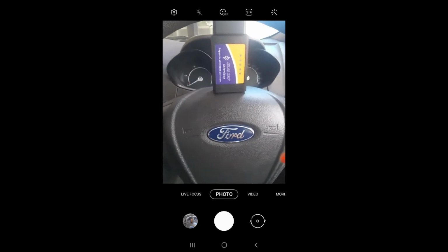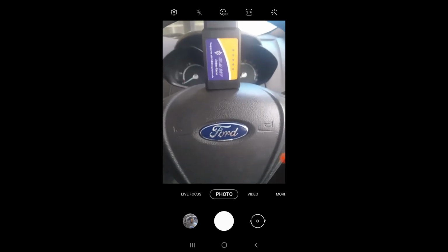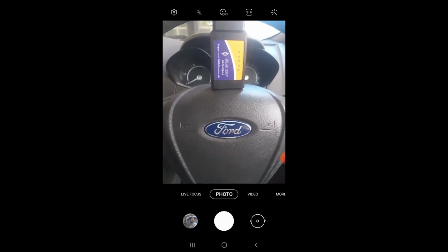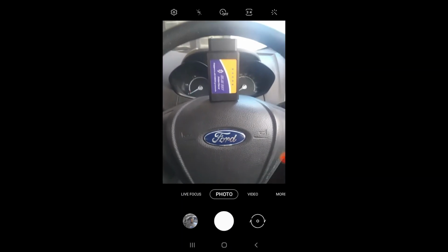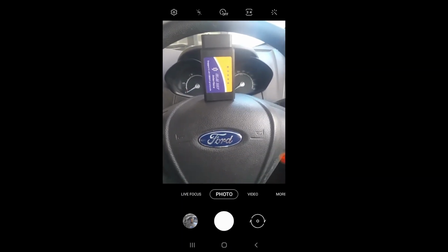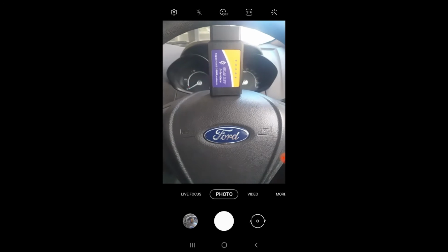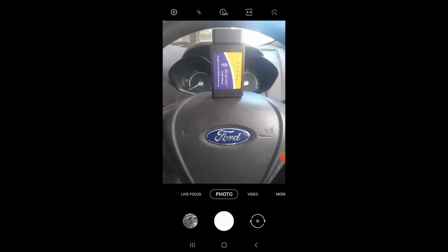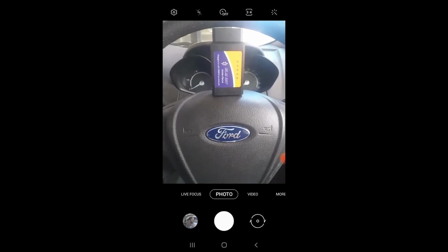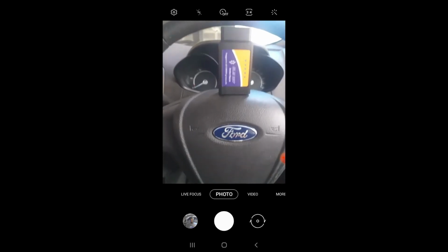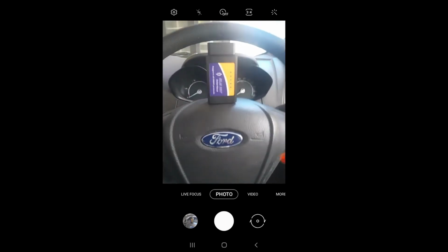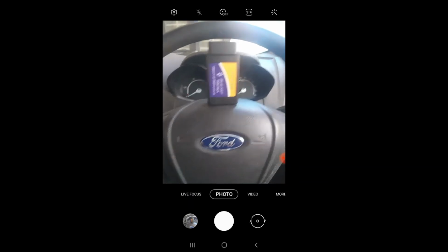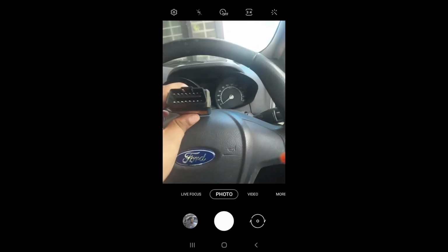We can also talk about PIDs, ID 7DF and ID 7E8, hexadecimal codes, like you can see 7DF, 7E8 and so on. One is the request and the other is the response that we get from the ECM. With ID 7E8, 8 ECMs can be supported by a CAN bus. So we have the 16 pin configuration over here, which we have shown.